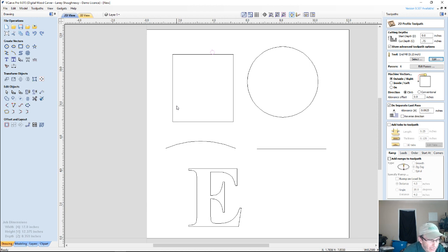You know, it's a little unlevel. You can really see those little stair steps, witness lines, on the passes, if that router bit is not hitting perfectly 90 degrees to the edge. So we definitely want to have trim, because even if we're doing the separate last pass, we don't want our profile cut cutting at an angle unless we were doing a chamfer.